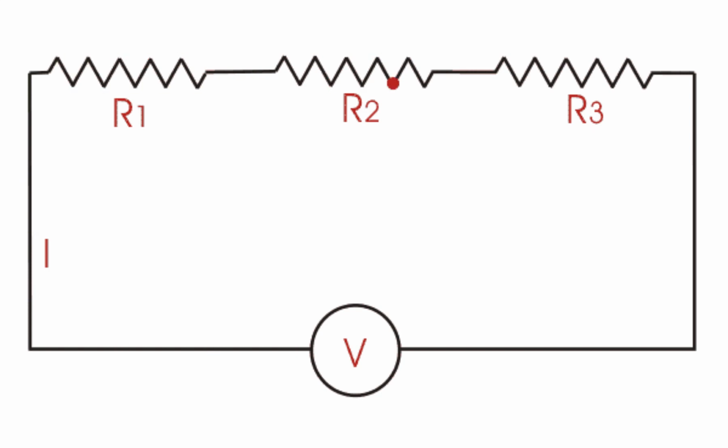One of the best examples of a series connected device is a fuse or a circuit breaker. Since fuses and circuit breakers are connected in series with the rest of the circuit, all of the circuit's current must flow through them. If the current becomes excessive, the fuse or circuit breaker will open and disconnect the rest of the circuit from the power source.